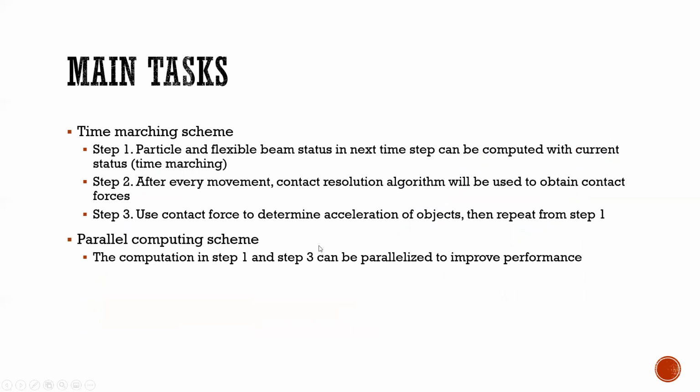And the overall marching scheme will be like this. The first step is to use the current status of the particles and flexible beam and march to the next step with a high order marching scheme like Runge-Kutta fourth order, which will give better accuracy. And after the movement, I need to do contact detection to check if there is any overlapping, so I can generate the correct contact force to push objects away from each other.